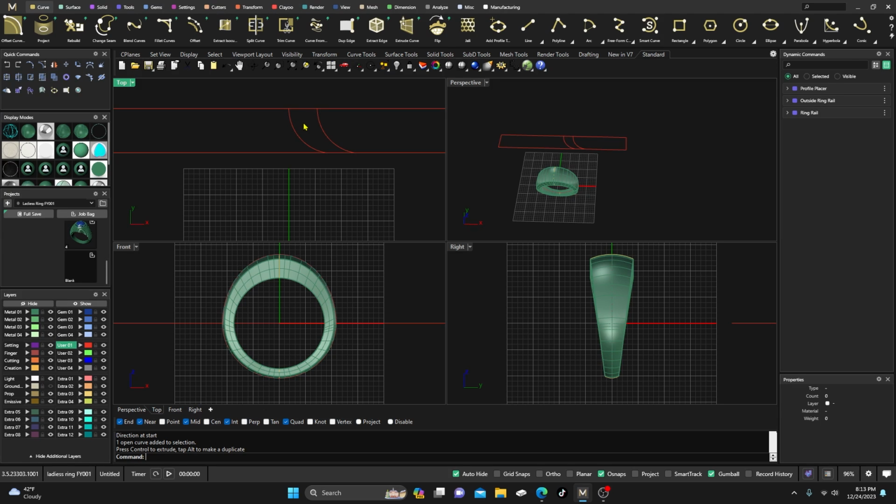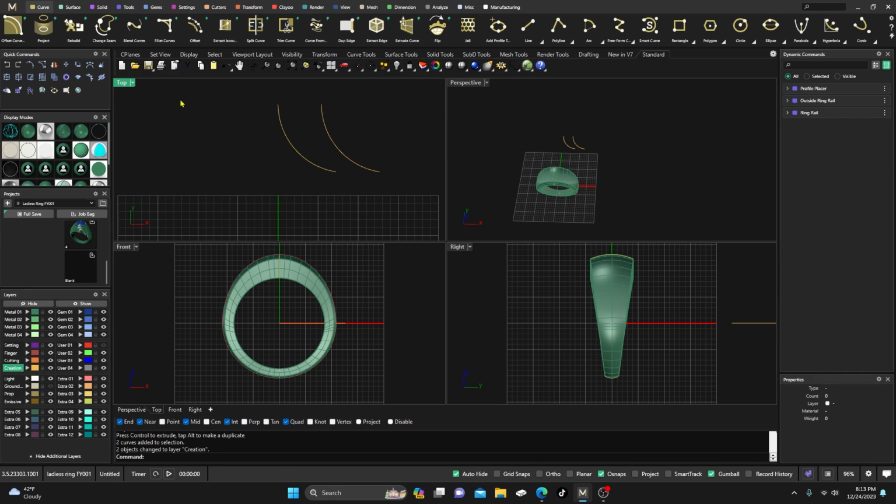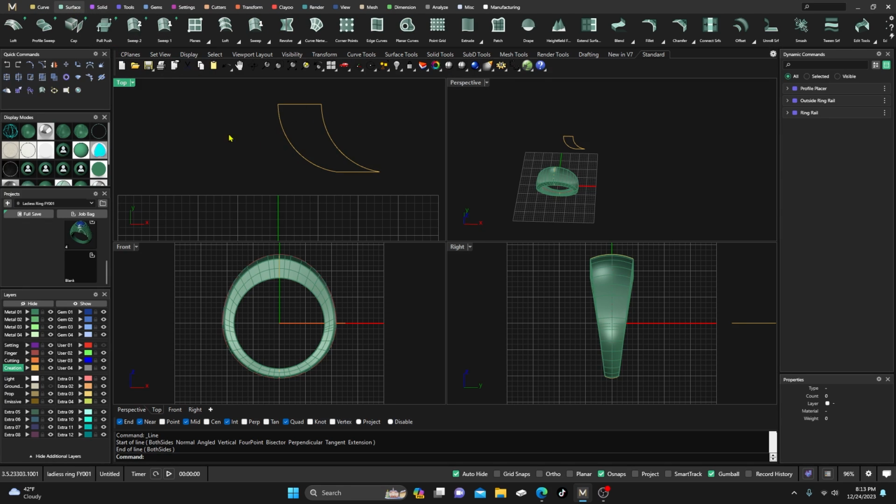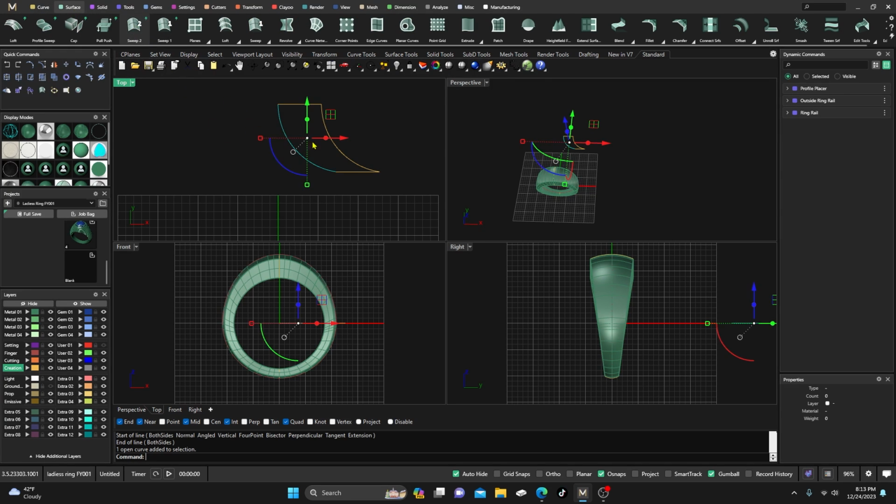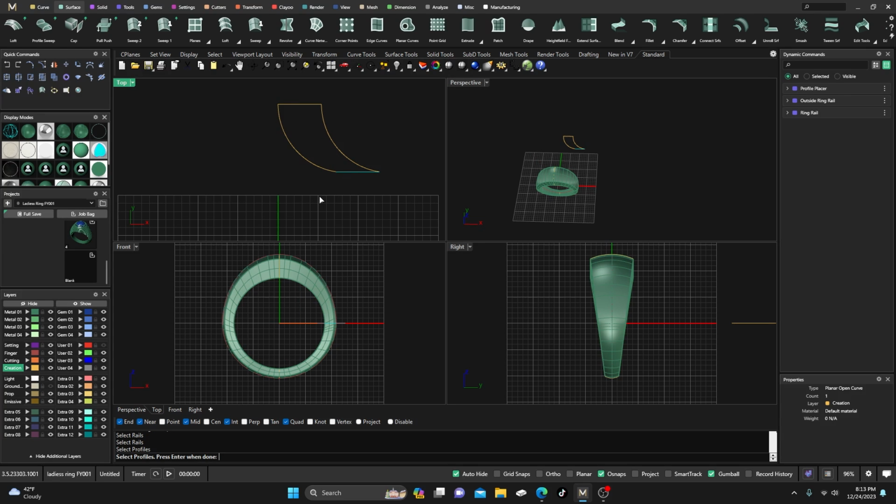First of all, let's go ahead and turn these to yellow. All right. And let's go ahead and hide this red here. You know, if you don't have to do a sweep 2 on this. I mean, if you do a sweep 2, you'll have to close it off at least on one side, right? To sweep it, and then go to your surface or your context menu and do a sweep 2, right? 2, 3, 4, hit enter.